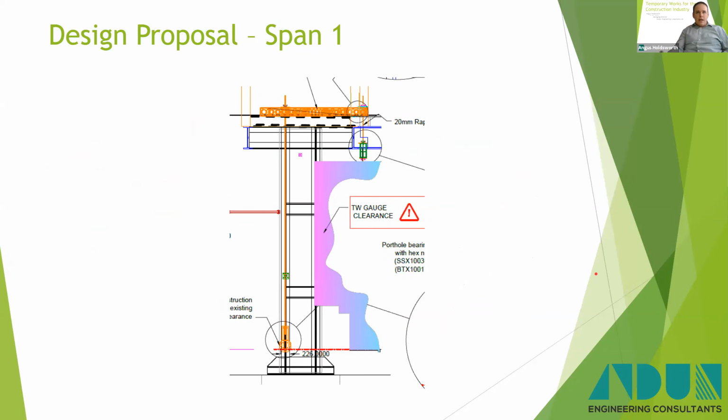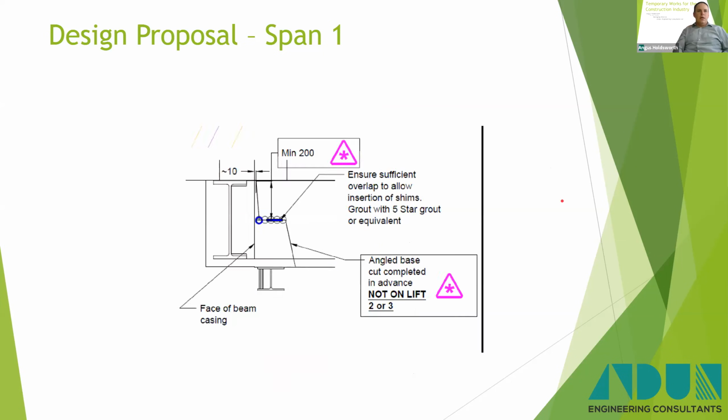You can see there in more detail, we've got this steel beam that sits underneath, and we performed a sit cut in the rear and the bottom beam, ready to lift it out. And you can see the strap that returns back down and picks up on the pier and gives us the reaction force we require to support that span there. Interestingly, you'll see that if you overlay the temporary works clearance gauge, the structure was already within it and everything else was just about outside it, which made life simpler.